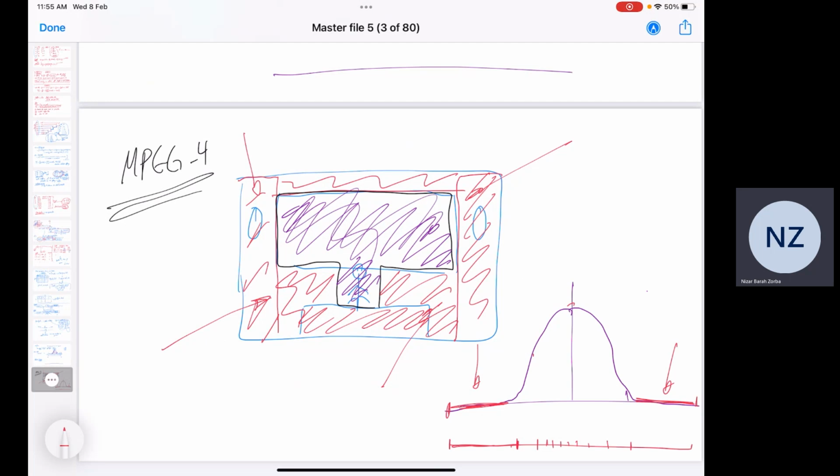So you see now the quantization levels don't have the same length. This one is very lengthy compared to this one, which is very thin or short. Why? Because the probability of something happening here is very low, so I approximate all of it to one single value. I don't care. But here the probability of change is very large, so I don't want to approximate a lot here. I want to do the least approximation. And in this system, how many levels do I put? 1, 2, 3, 4, 5, 6, 7, 8, 9, 10, 11, 12.